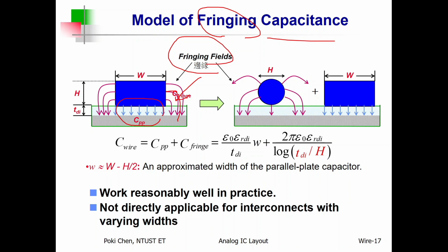Alright. So it is really harmful for wiring, for interconnect. But again, if you would like to design real capacitor, then fringing field can help you a lot. The more curvature, the better for real capacitor. However, the more fringing field for interconnect, for wiring, the worse.